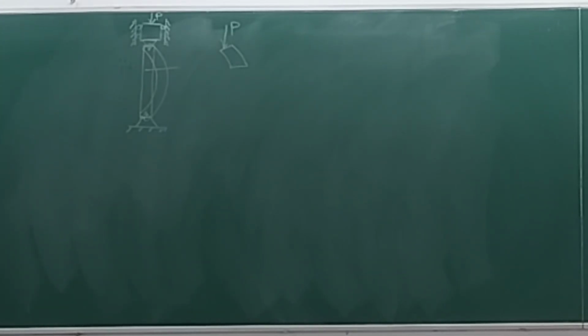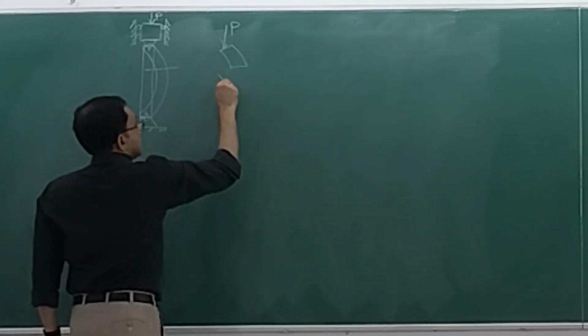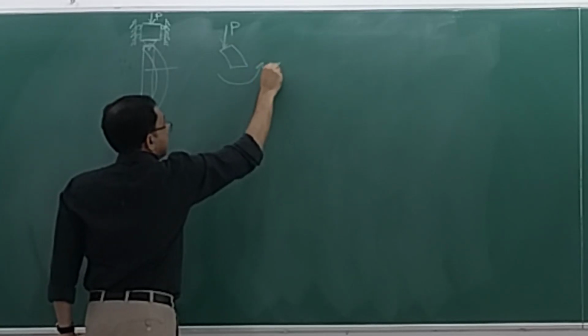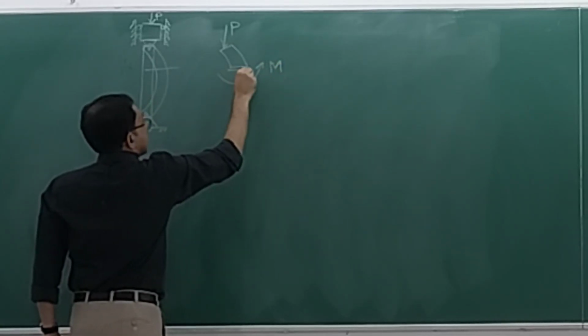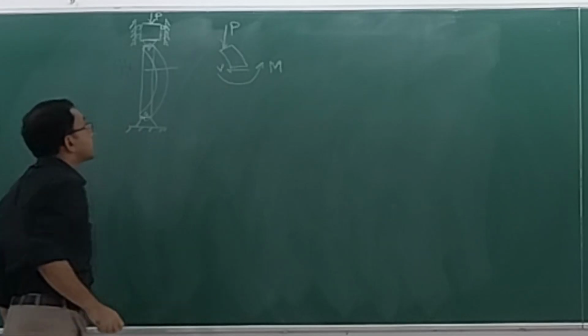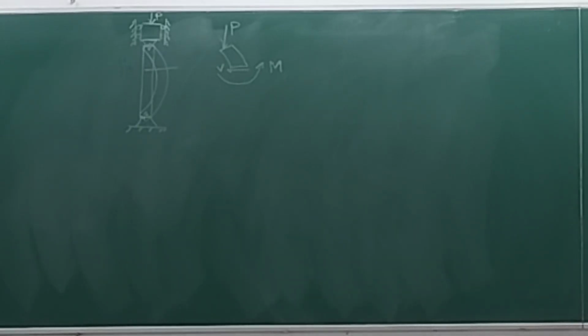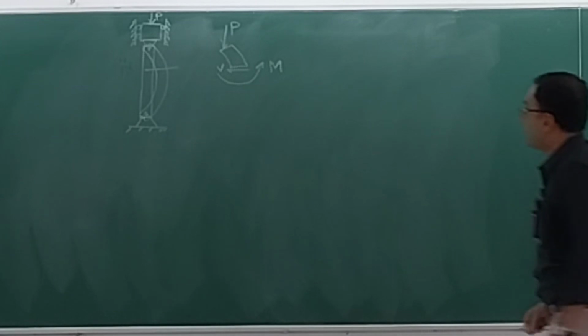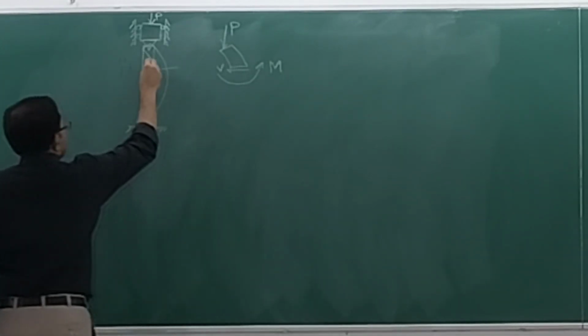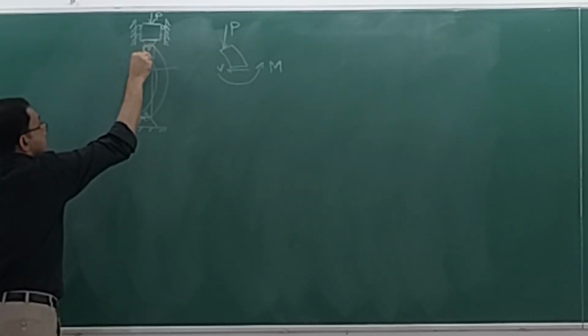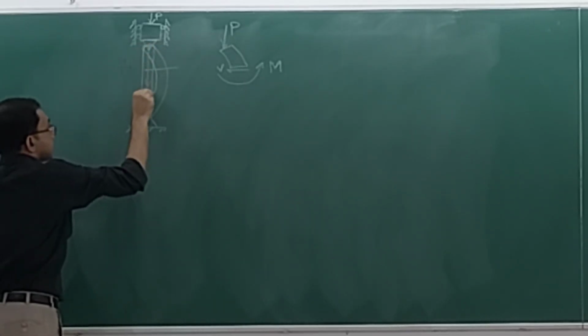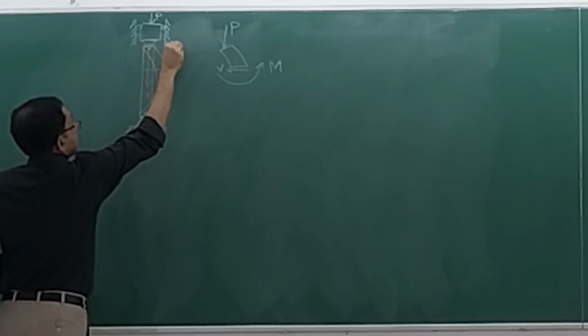So this is a cut section. We are familiar with how to deal with it. So this is the moment M. There will be a shear force V. Please also note that the way that I set up my coordinate axis is very, very important. What I will do is put the x-axis downward like this and the y-axis like this.